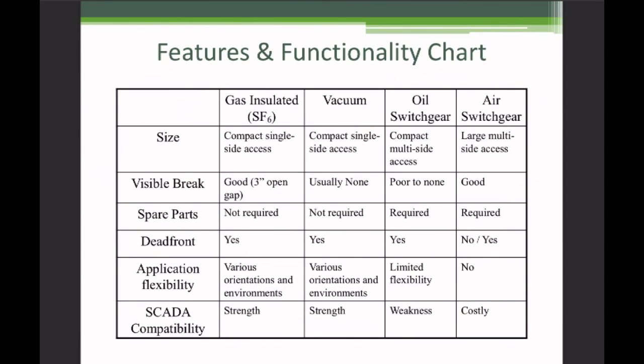So wrapping it up, in summary, what do we got? We've got our 4 different insulating materials. We've got some comparisons on visible break size, whether they're dead front, how flexible they are, and whether they're any good for remote control.